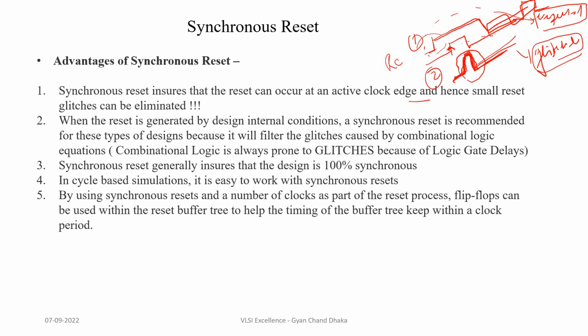Similarly, advantage 1 is based on the external reset. If the external reset is glitchy or there is noise on the external reset pulse, then the synchronous reset will make sure that any kind of glitch or noise will not affect the design.